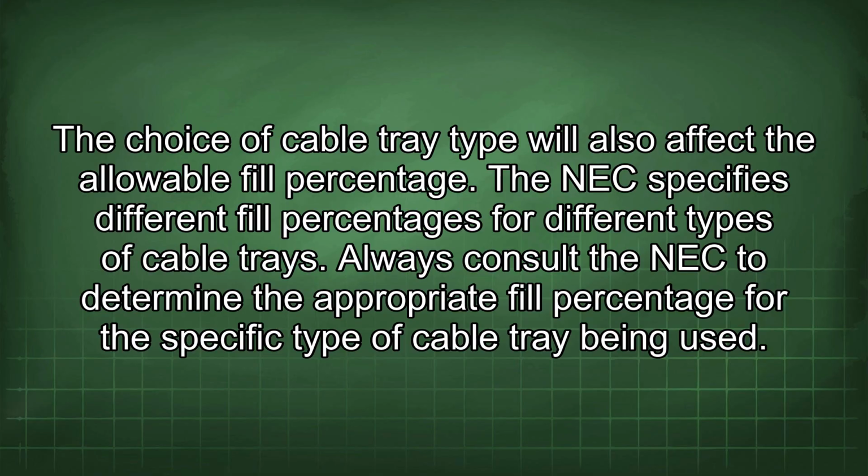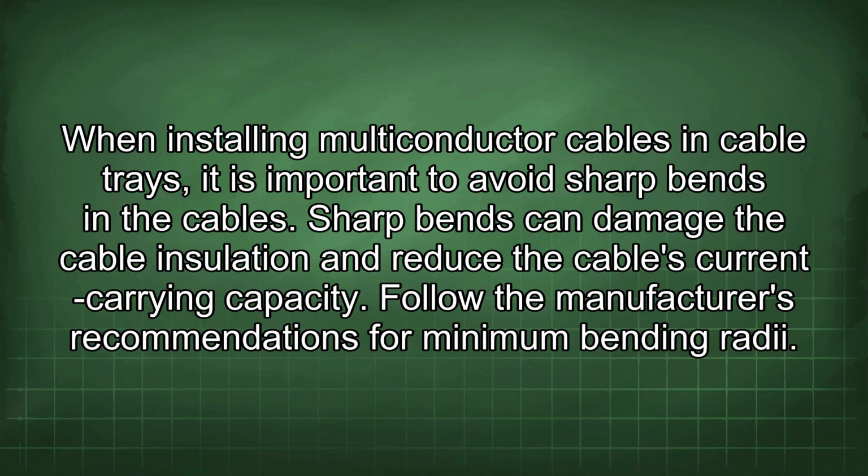The NEC specifies different fill percentages for different types of cable trays. Always consult the NEC to determine the appropriate fill percentage for the specific type of cable tray being used. When installing multiconductor cables and cable trays, it is important to avoid sharp bends in the cables. Sharp bends can damage the cable insulation and reduce the cable's current carrying capacity. Follow the manufacturer's recommendations for minimum bending radii.